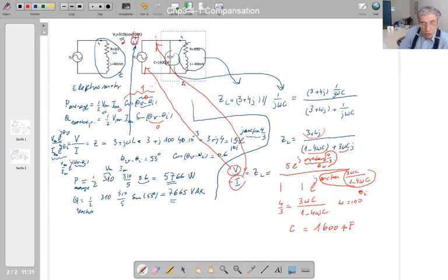So if you do this calculation now, I know that Q, the reactive power, is equal to 0, and P is going to be the same as this, 5,766 watt. So what is this current now? Here, this is the current, the maximum value current. After you put that omega equal to 100, that's your microfarad, you're going to find the maximum value of this current, which is this, isn't it? So that is the maximum current here. Let me write it here. So IM